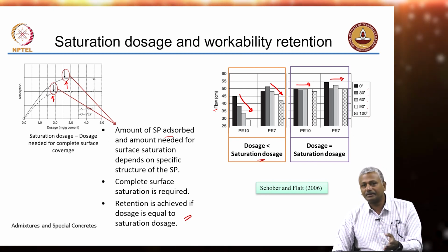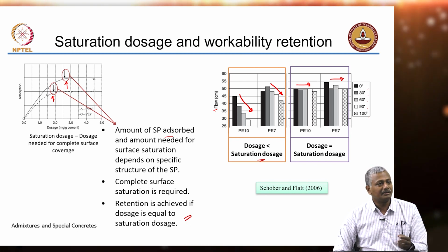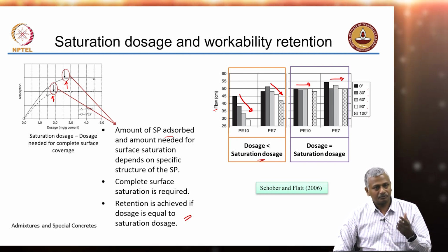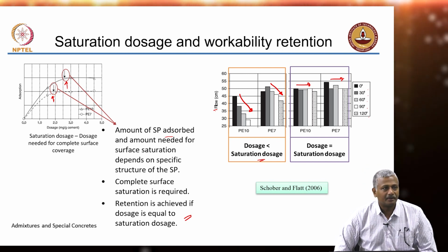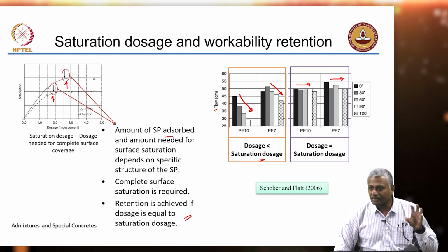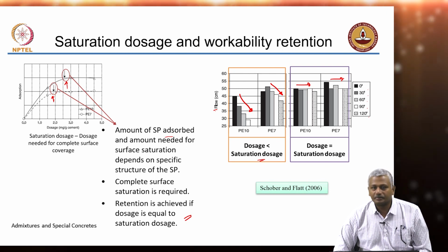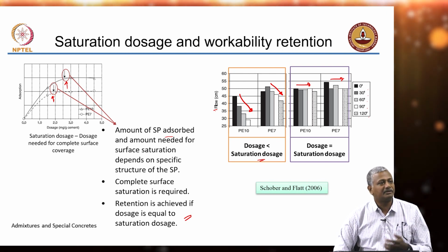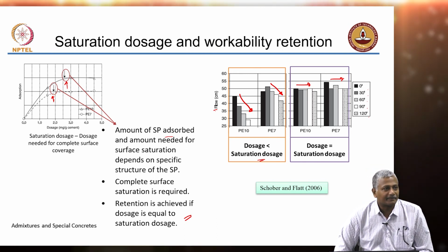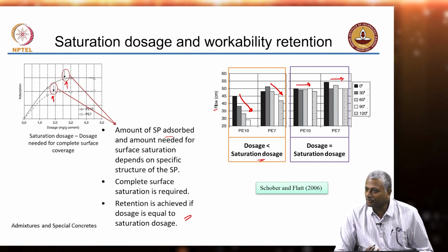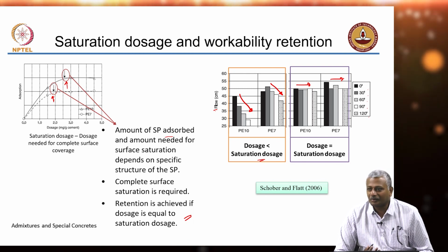They ultimately determined that the strength of the cubes was not coming close to the 28-day strength. So, we went and took cores from the columns, and for an M35 concrete, the strengths we were getting were between 10 and 15 megapascals, 10 to 15 megapascals for an M35 concrete.